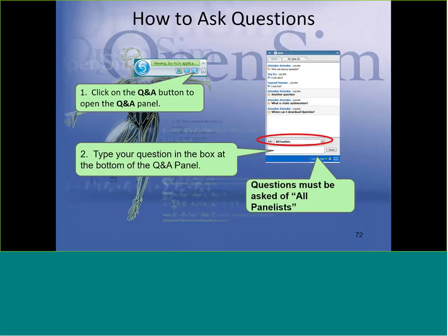I would say that the best way is probably to start simple. Having a really complicated, multi-driven simulation with multiple muscles can be quite daunting. So having simple simulations where you have maybe just one muscle tendon unit actuator, and then understanding all the different components that go into it and how each variable can affect your ultimate answer would be probably the best place to start.